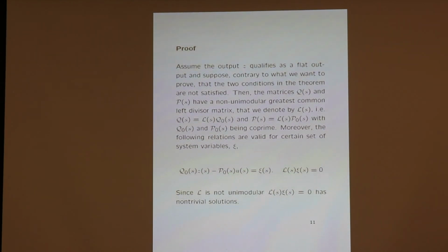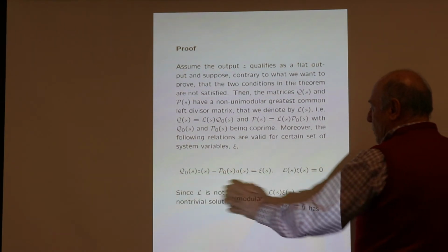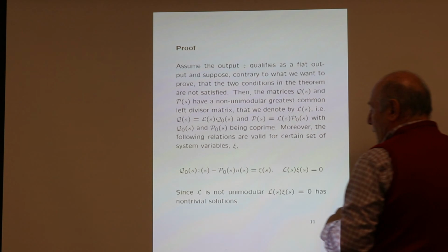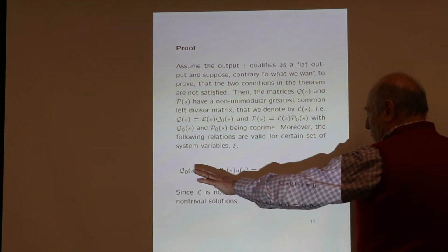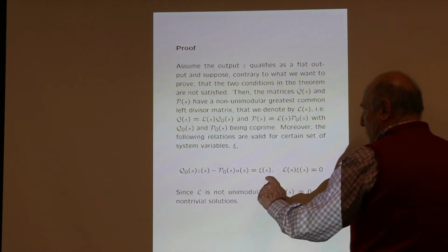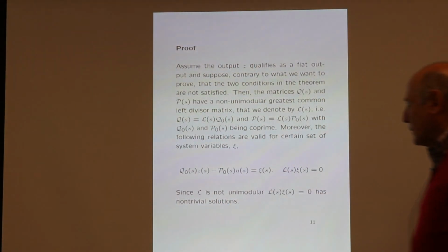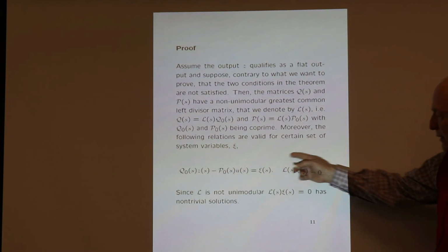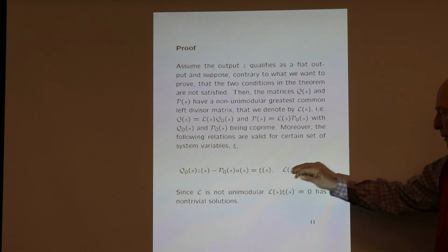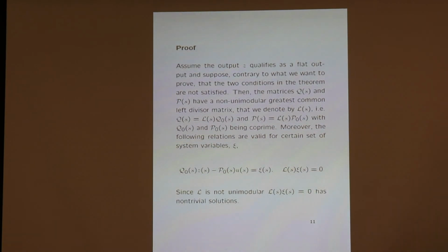existence of a common factor which is non-coprime, in spite of the original matrices being coprime, but the product of a common factor will destroy the issue of controllability, because that factor there, which is non-unimodular, will be able to produce a 0 on this vector C, which is responsible for the right coprime representation. If we do that, then evidently C is satisfying a set of differential equations by itself, one equation for each row vector of the matrix L, and therefore C is not controllable.